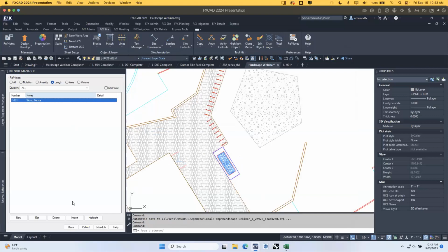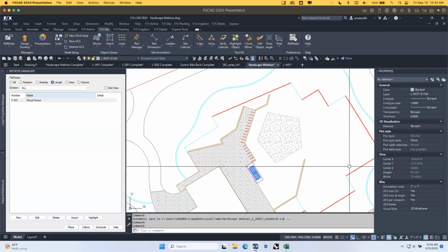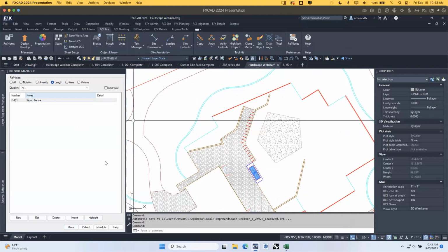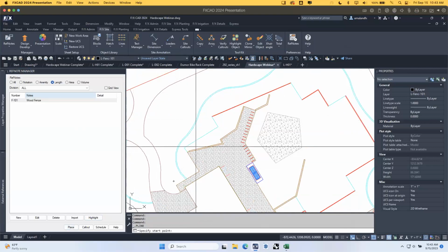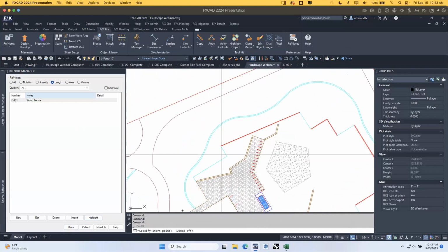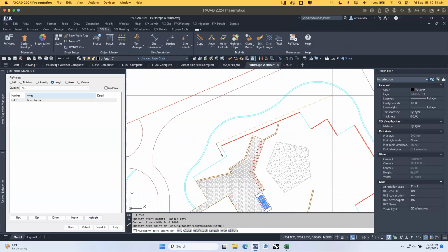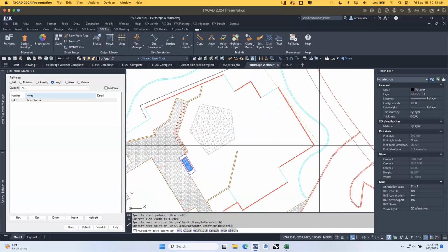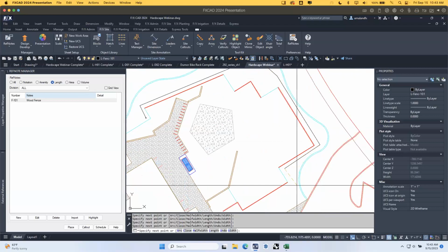And we're going to grab that and I can place it. So it will actually calculate any line that appears on that layer. So if you already have things in here, you can select them and move it to the layer that you just created in your list. Or if I grab this one and click Place, it brings me into the polyline command, but with that layer chosen to start drafting on. So I can go F3 and I'm just going to put in this fence a little bit around here. We'll go up here and then over and down and over.